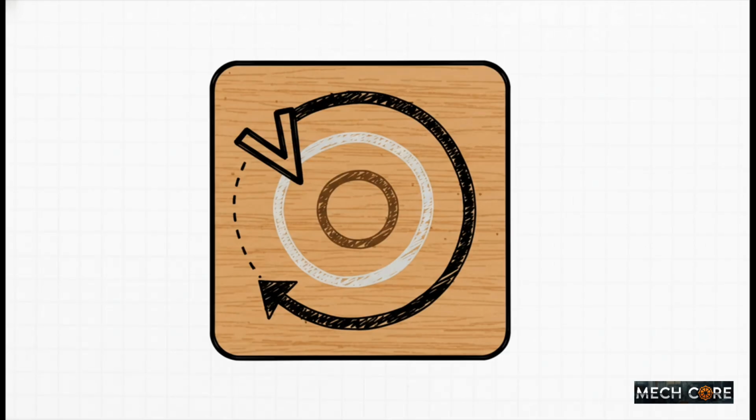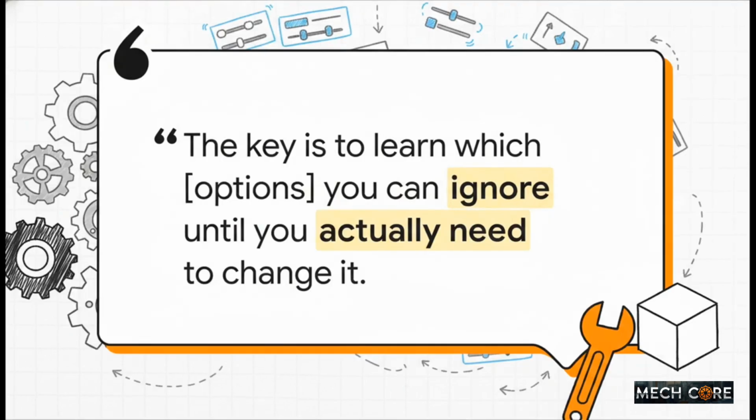And number 4 is trace. Honestly, the easiest way to think about this one is engraving. A trace toolpath just follows a line or a sketch right on the surface. It's not for digging deep, it's for adding those fine details like text or that cool spiral pattern on our coaster.